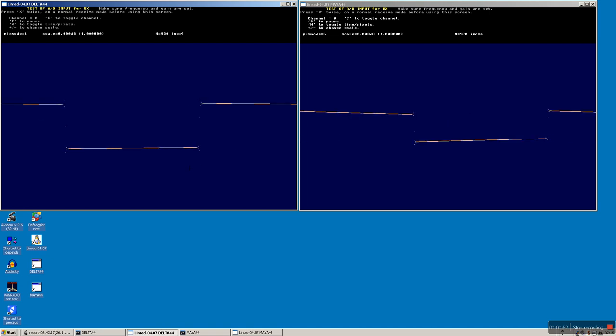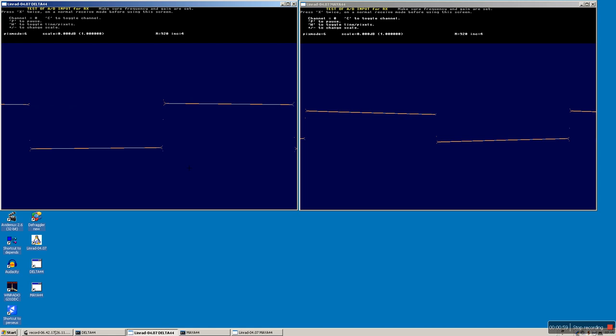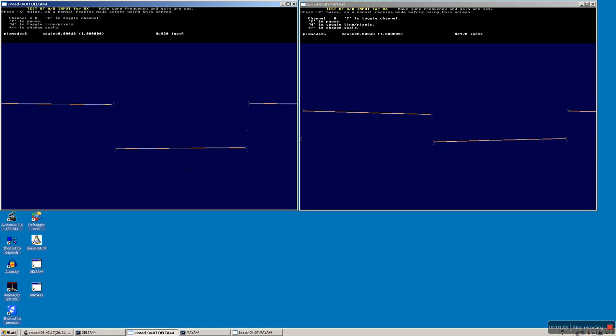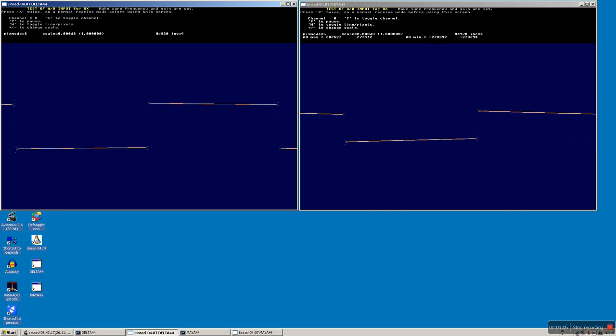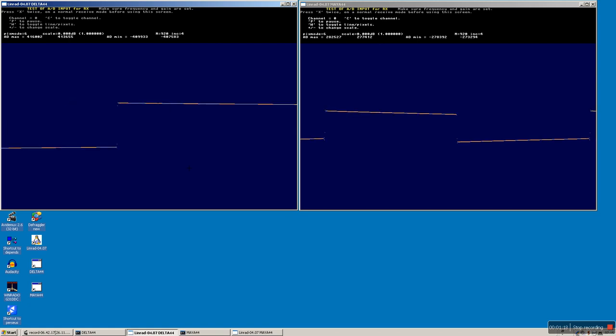And you can see the difference between Delta 44, when it looks very much like a square wave, and the Maya 44 when there is a high-pass filter, so the square wave is sloping, and this is a fairly high audio frequency. It is 100 Hertz. So I reduced the frequency a little bit.